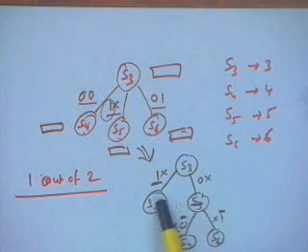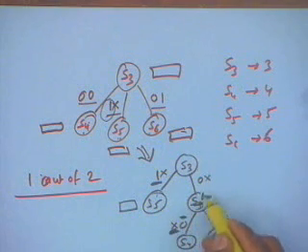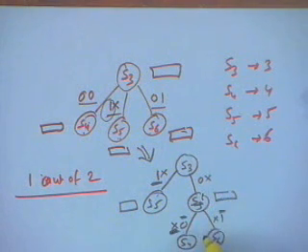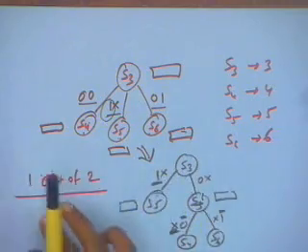So this decision is being done by the sequencer, because I need to generate a separate set of control signals if this is true, and I have to generate a different set of control signals if this is false. And this decision is being taken by the sequencer. The role of the sequencer is generating the next address. So if you consider your state machine, the role of the sequencer is to generate the transitions. So wherever you are making a transition, you need to generate that.